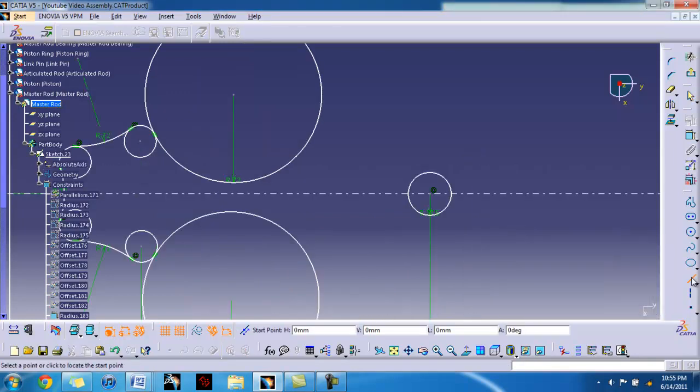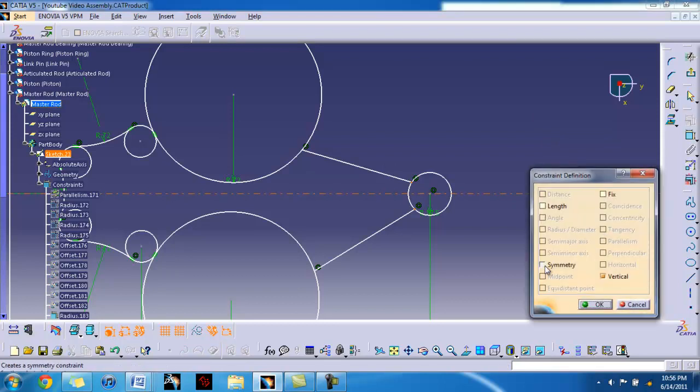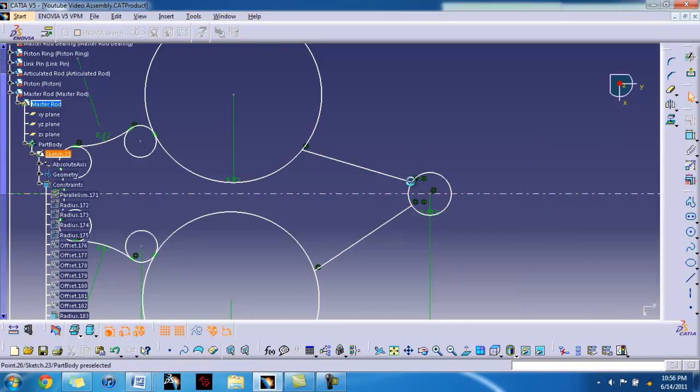We're going to create 2 lines that are attached to both the 17.5 radius and the larger circles, making sure that no other constraints are made. And another. Alright, the points on the ends of the lines on the circle, we're going to make them symmetric about the axis. And we're also going to add a constraint of 18. It's going to be an offset constraint.